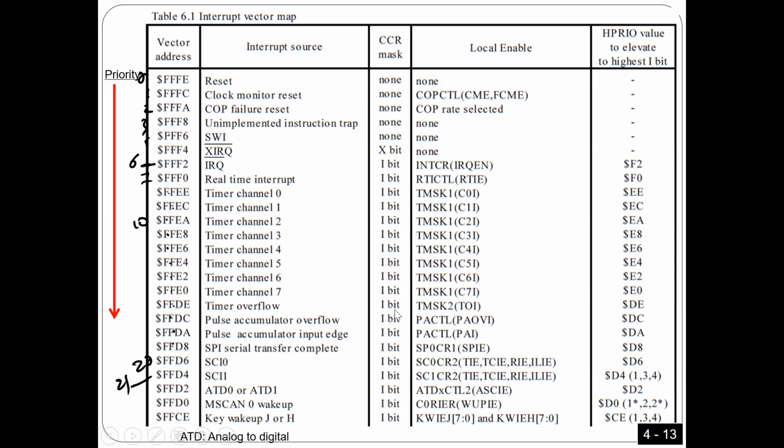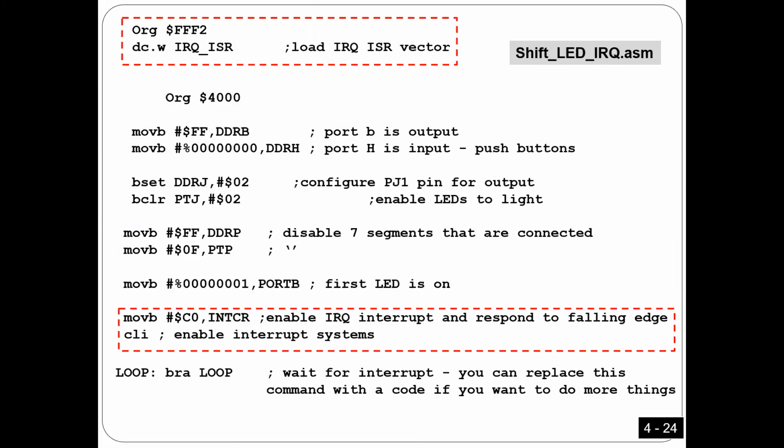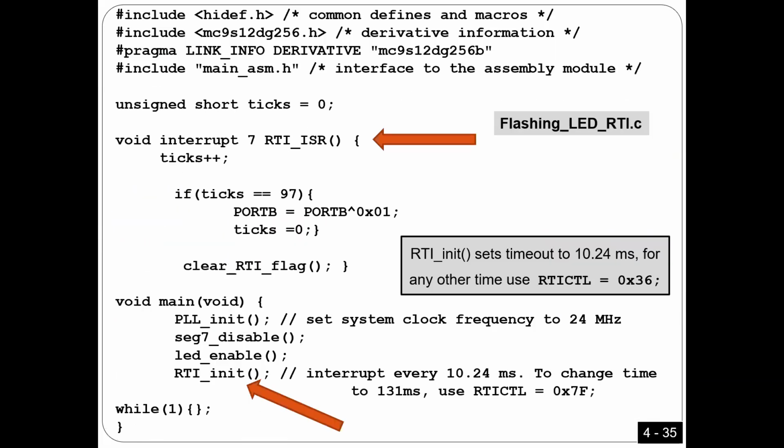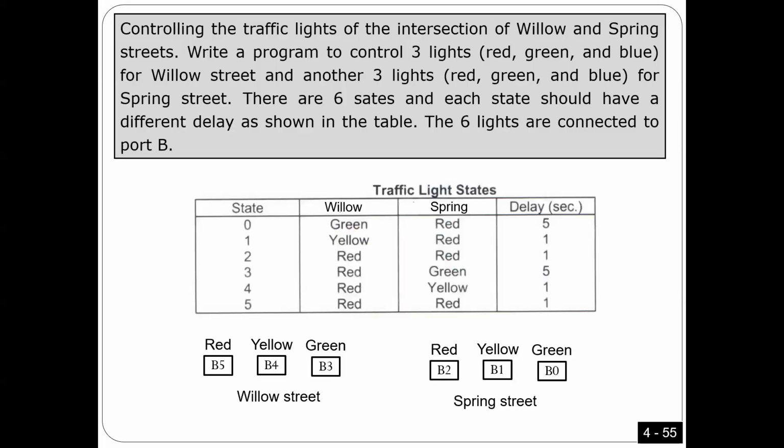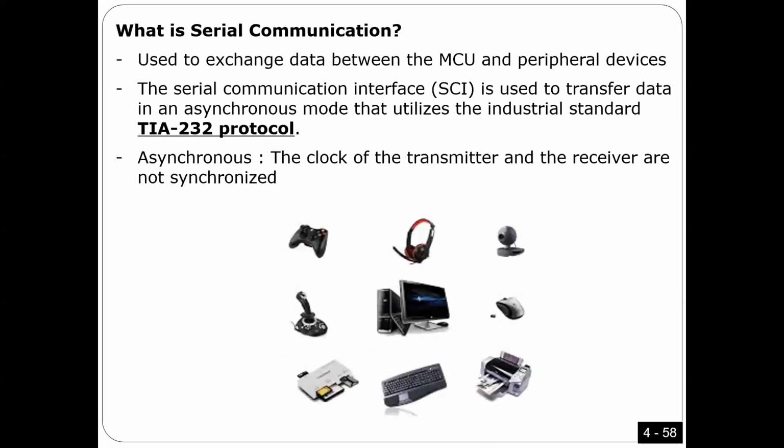Same thing. Until now we used the number 6, used the number 7, and now I'm going to use 21. And when I go to the timer system, we're going to use the numbers 7, 8, 9, 10, 11, and so on. So very easy, we just change some numbers. Anyway, for the interrupt subroutine, you have to use number 21 just to tell the C language this is the interrupt subroutine for SCI1.